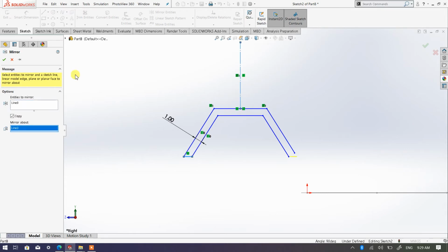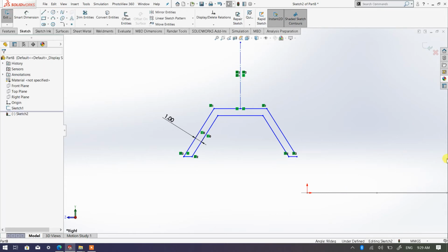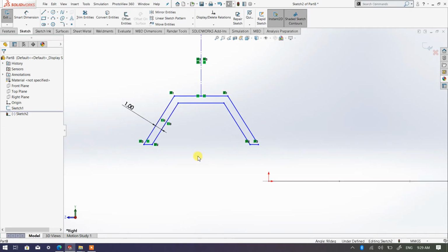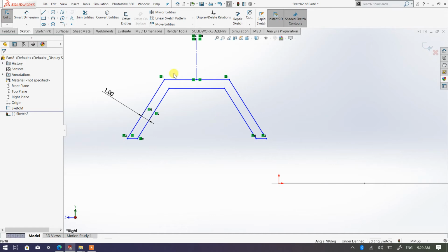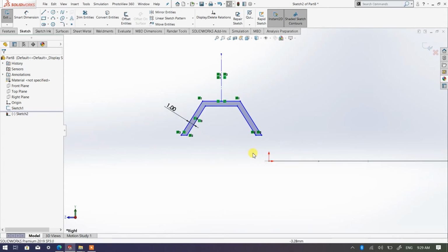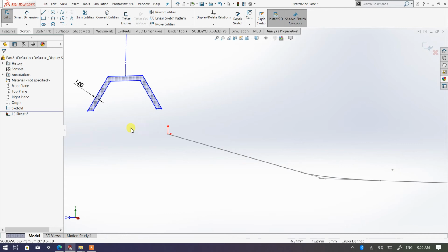Either way, you can straight away create a line and then do the same thing which we have done just now at this side, or even as what I did show you just now, using mirror. So I'm going to use mirror, and then I'm going to extend this line to here, right? So once after confirm, it's not necessary for me to have it fully defined.